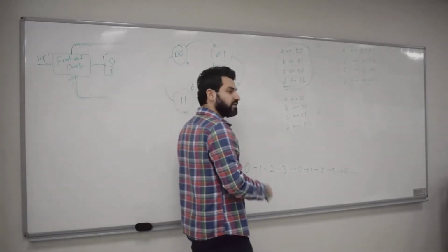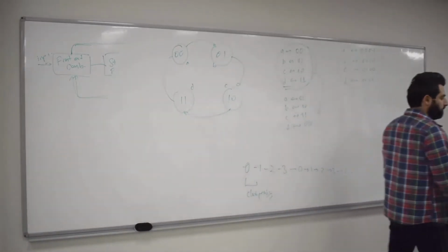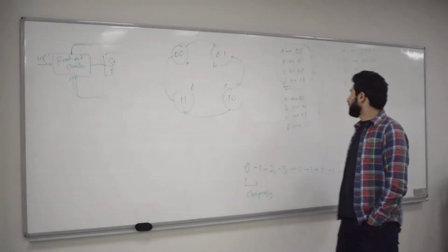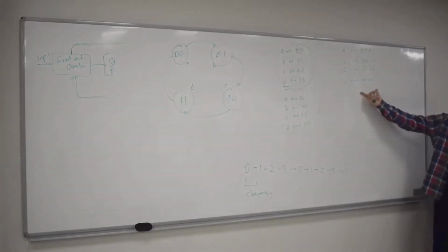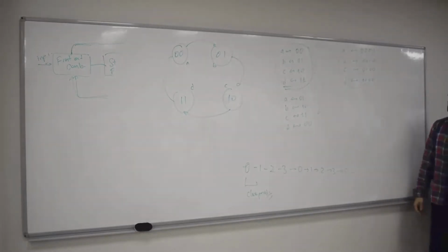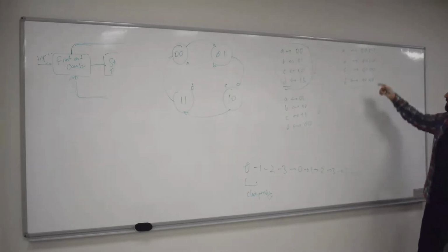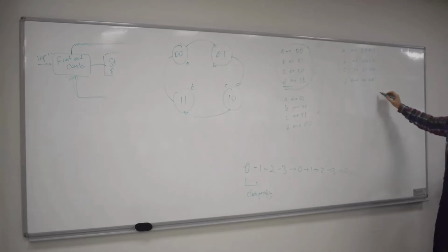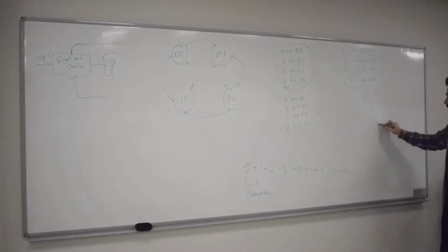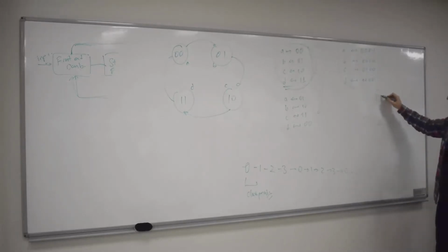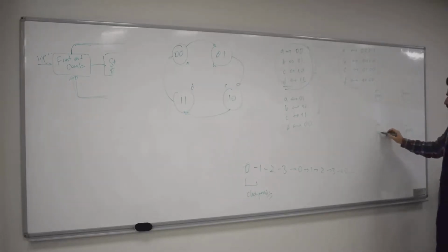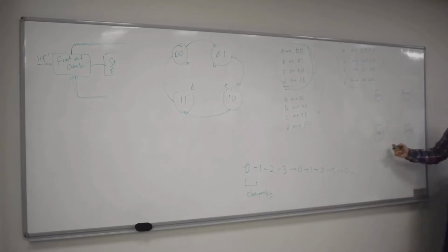We can go ahead and design using our standard approach a counter using 4 states like that. Or you can use this assignment, okay, this assignment to create a counter using those 4 states now. In other words, instead of doing this kind of mapping, you can do the following kind of mapping: 0001, 0010, 0100, and 1000. That's another possibility, okay, doing this type of mapping.